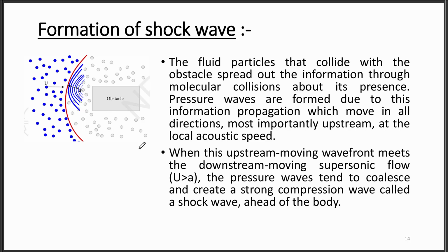When the flow is supersonic, its u is greater than a, then this pressure wavefront will meet this supersonic flow. So what will happen due to this? All these pressure waves will coalesce and create a strong compression wave. This strong compression wave is what is called the shock wave, which is formed ahead of the body.